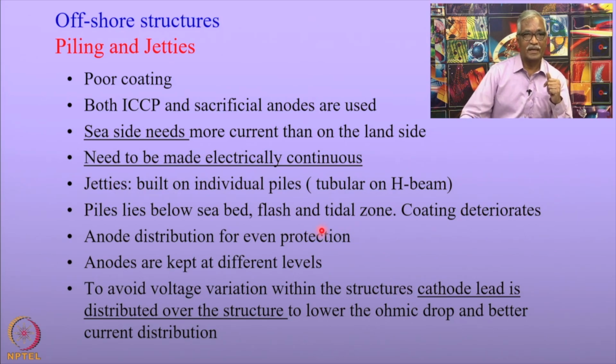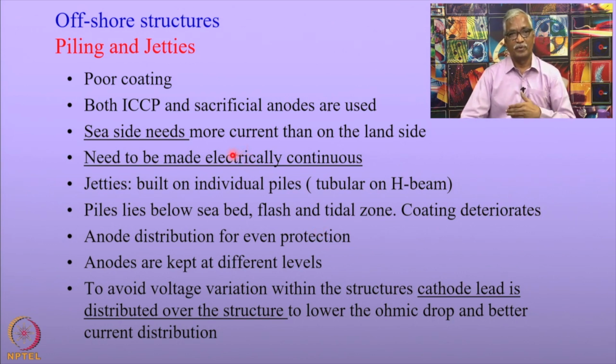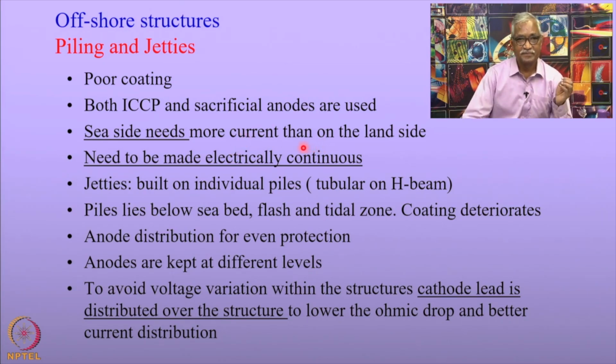Okay. And again, if you have structures on the offshore and the onshore connected, the one on the seaside requires more current than on the land side, and they need to be made electrically continuous.